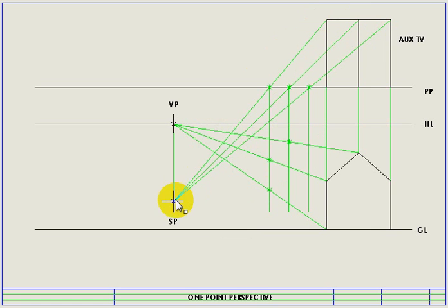And remember what I said, when I look from my stationary point from the left to the right, anything behind these 2 points will be this line, that line, and this point will then be hidden detail. If I follow this point, which would be a hidden detail, note that it would fall right behind the building here somewhere. It'll be in line with this here. And the bottom point of that one would also be in line with the bottom point over here. So I won't be able to see it. I'm not going to be drawing those in hidden detail at all. I'm just going to trim this and clean it up nicely for us.